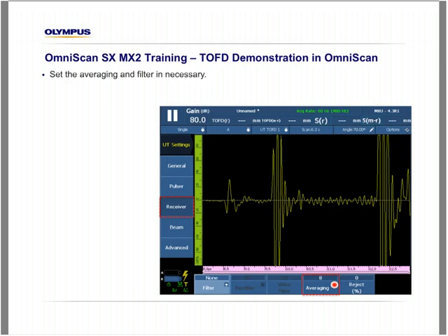The shorter the cables are, the less averaging you're going to see. In most 2 or 3 meter cable inspections, we might not see any benefit at all to averaging. So use what works best based on the SNR of the signal as you experiment with this. It has a very low effect on the overall PRF because these are individual A scans.